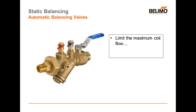The same argument can be made for our automatic balancing valve. Let's say that branch run required 100 gallons a minute, and so we put a 100 GPM automatic balancing or flow limiting valve in place. What happens if there's only 20% of the flow? What does this type of device do at reduced flows? Well, not very much, unfortunately.